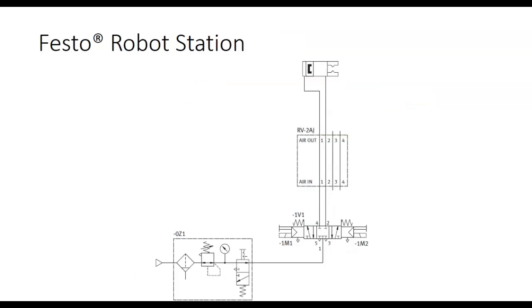This is what they're using on the gripper on the Festo line. All this is showing is that it's running through the piping through the robot. What would that be? Five port, because it's running 5 ports. It's running two exhausts, so it's 5 ports, right? And what's the exact advantage of two exhausts? They exhaust on both sides. That makes sense? So if you exhaust it on one side, then one of them is going to have to go a long way to get out.